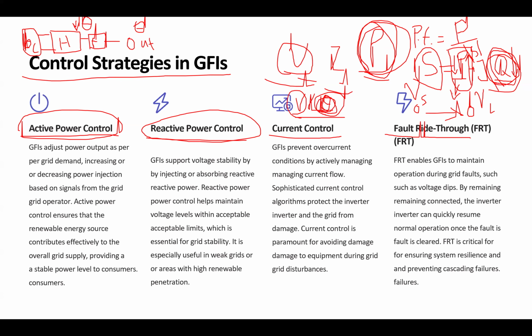If we wanted to inject a certain amount of power, we need to set the voltage at the output of our switches at theta 1. So if the voltage at the end of the switching has a phase of theta 1, when the voltage at the beginning of the switching has no phase, so it's 0, how can we model this difference of the phase angle?